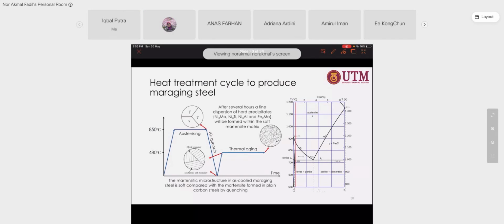Next is thermal aging. After several hours, a fine dispersion of hard precipitate forms. Rather than forming carbide, it forms hard precipitates between the alloying elements, such as nickel-molybdenum, nickel-titanium, nickel-aluminum, and iron-molybdenum. There is no iron carbide and no titanium carbide, because carbide is brittle.